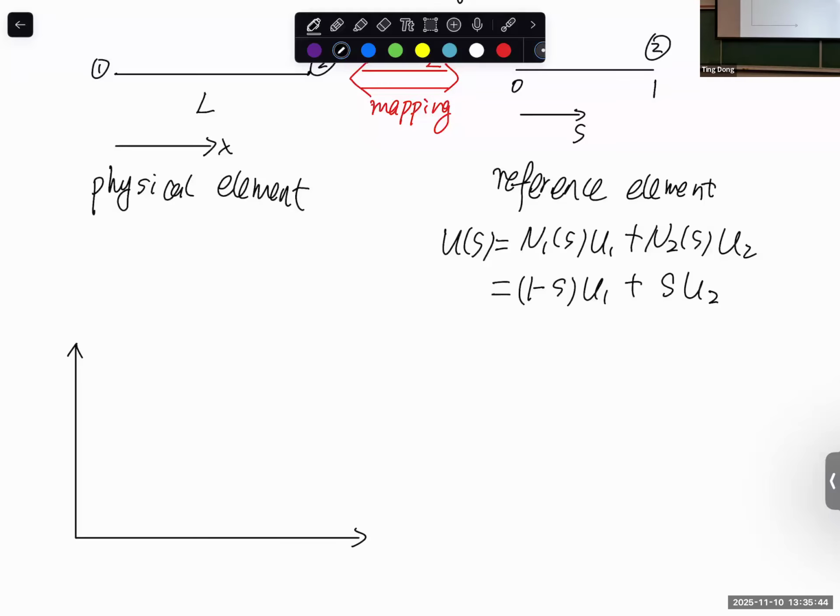For this quadrilateral element, the four edges do not necessarily run parallel to the coordinates, and the interior angle does not necessarily have to be 90 degrees, which in all situations you need for irregular shapes. Let's use this as a general situation in XY coordinates, with node 1, node 2, node 3, node 4. And whatever we derived in the previous chapter doesn't work.